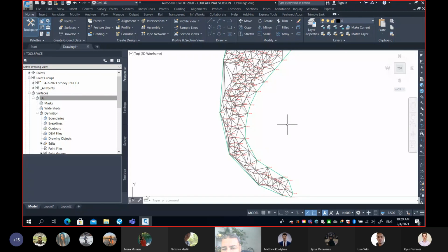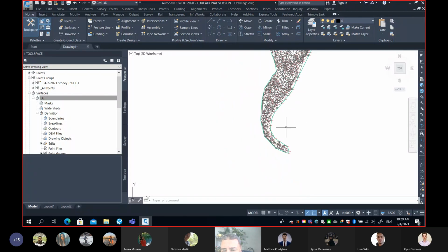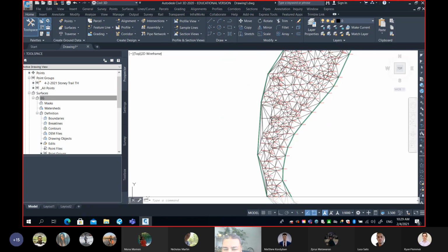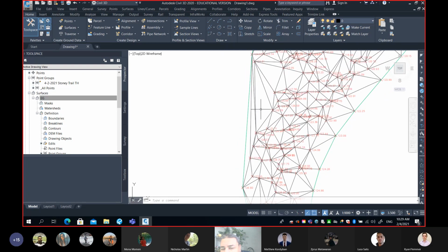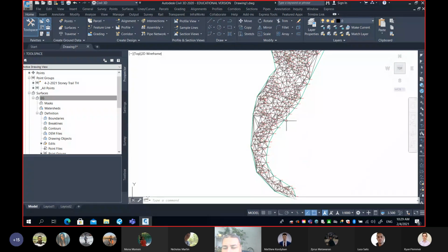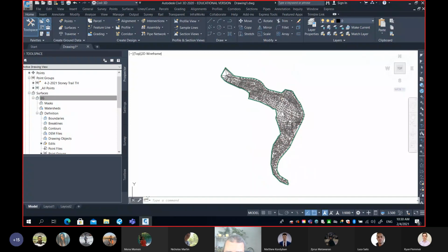Sometimes the cleaning is very easy because it's very obvious that this area is wrong. But sometimes it's very subjective. And maybe some of you will question, Tahir, should I remove this area? To be honest, the one who can answer this question is the surveyor. Maybe he will tell you, get rid of those few triangles. Or maybe he'll say, you know what, this area could be okay, like flat or something. But for sure, this area was completely off. Anyway, so far you have seen the first edit, and the first edit is removing some of the triangles.